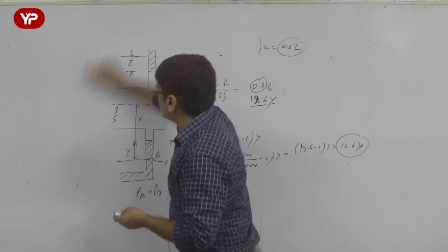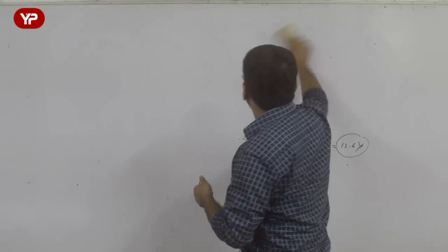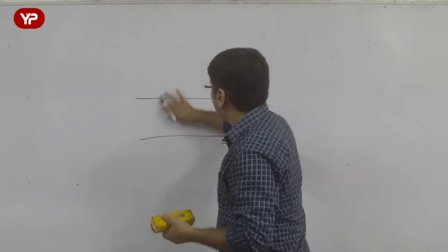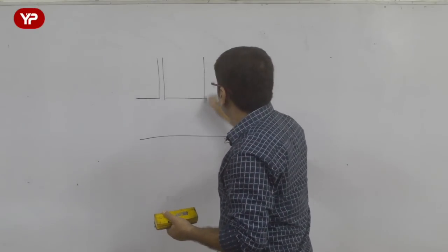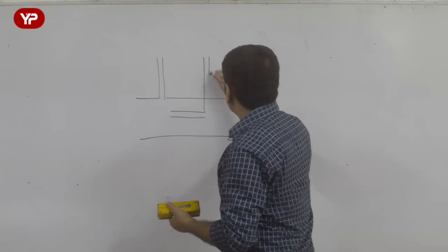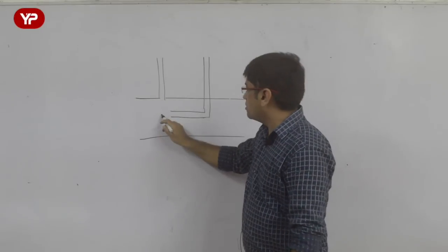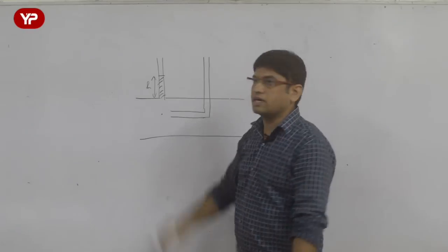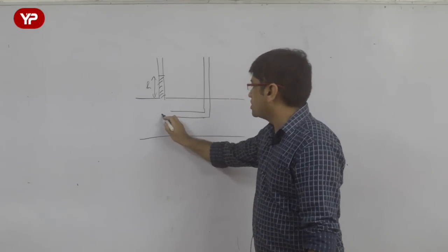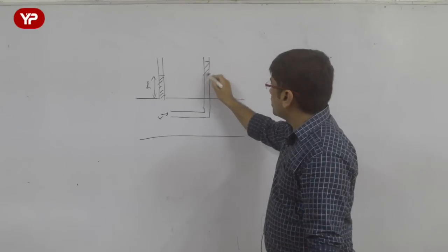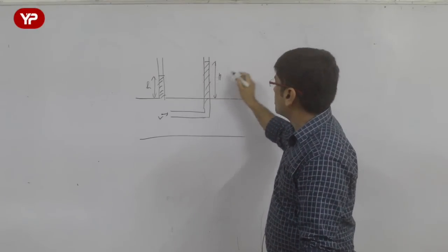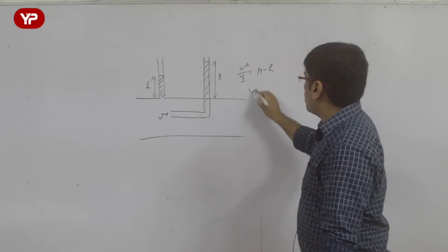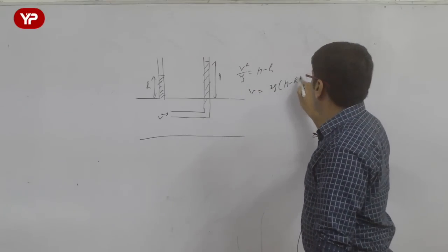And then we have already discussed the analysis of the pitot tube, that pitot tube analysis can be done. This is the typical pitot tube. I attach the piezometer and attach the pitot tube. Now this is the piezometer. Whatever pressure is here, this piezometer is going to give me the value of static head here. Whatever is the velocity here, that becomes 0, and I am going to get the stagnation head here, capital H. And with the pitot tube you get V square by 2g is H minus small h, or V is equal to root of 2g times H minus small h.